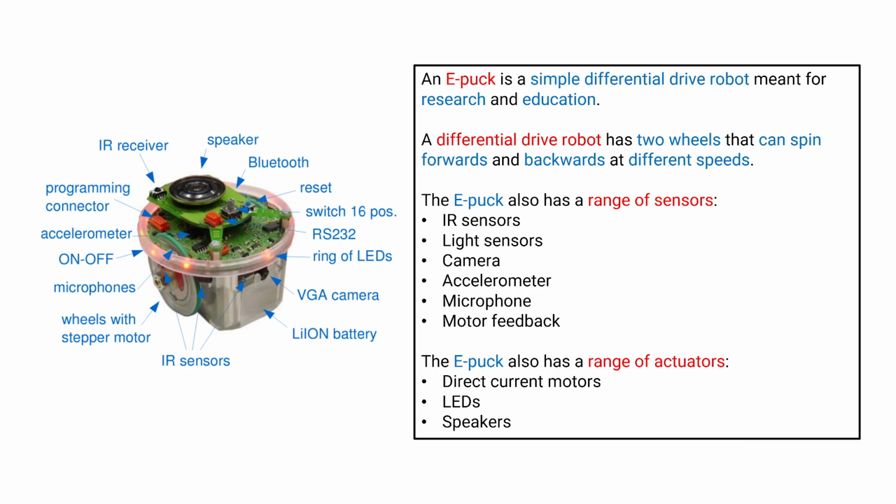In addition, we have them equipped with a bunch of different sensors and actuators, not just the wheels, but in particular, there are infrared sensors, which are usually very simple, easy to build sensors that are used for proximity, so you can detect how close you are to a wall or another object. It works by shooting out a small little infrared laser, and that bounces back, and it measures the intensity of light bounced back. Higher intensity usually indicates that there's an object that's closer by. And of course, infrared sensors are, like I said, fairly inexpensive and cheap to build, but they're also not going to give you the highest fidelity of information. They're good for detecting objects and so on, but they're not great at detecting much else.